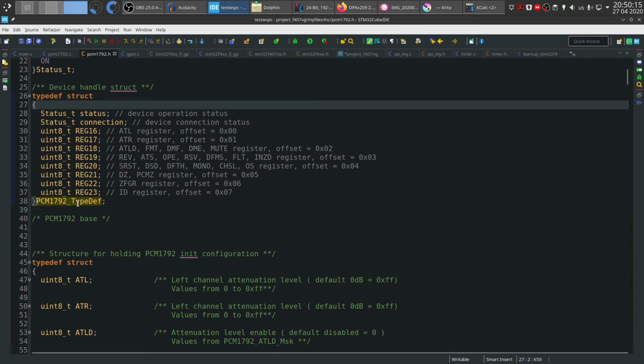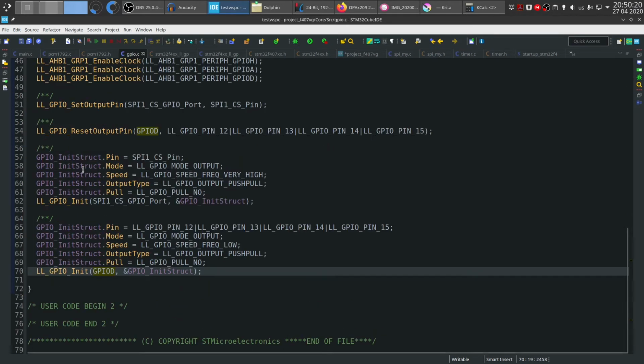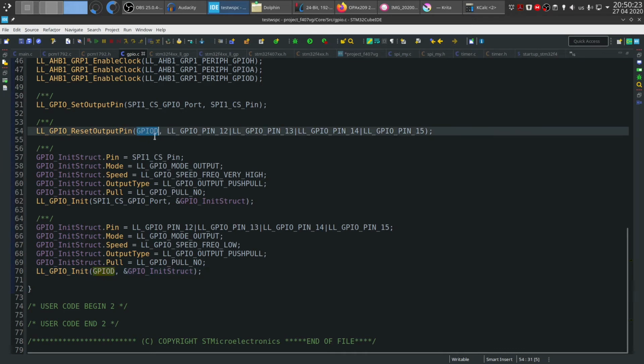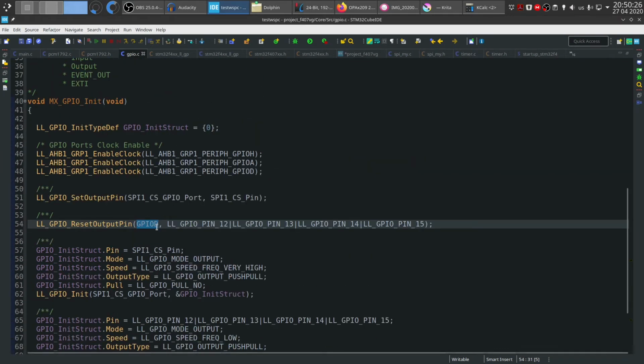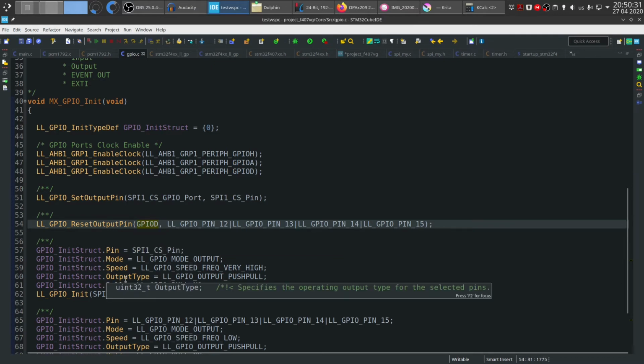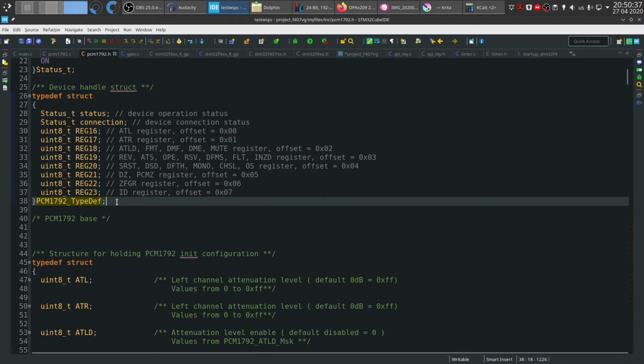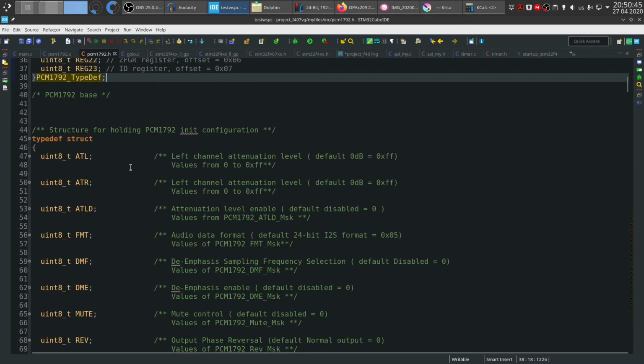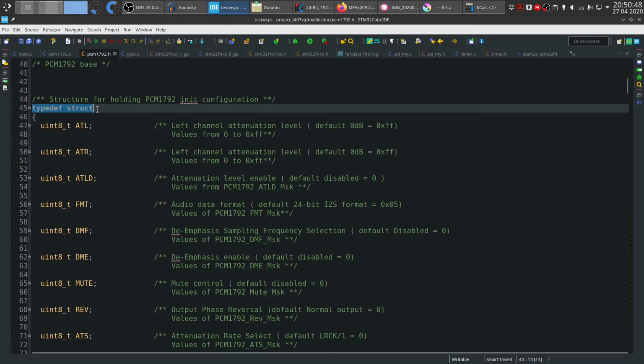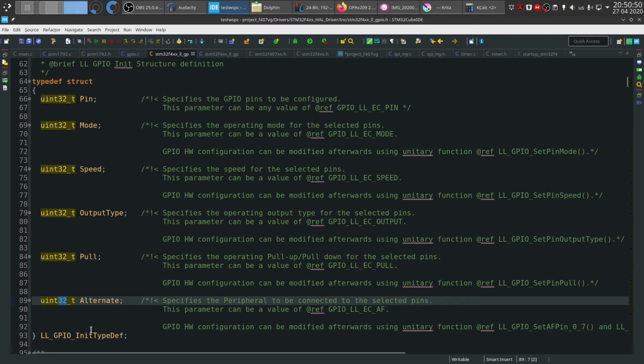So this is just the core definition that we're going to use all over, like the GPIO-X in this case, like using GPIO-D over here and GPIO-A. We're going to use this in the same way as GPIO-D or SPI1 or timer1 is used all over the code. This is what we're going to refer to all the time. So this is going to have to be accessible and stored in static memory, so it's available all the time. The next structure is the long structure that we talked about over here. These are the actual settings. So this is not the state of the machine.